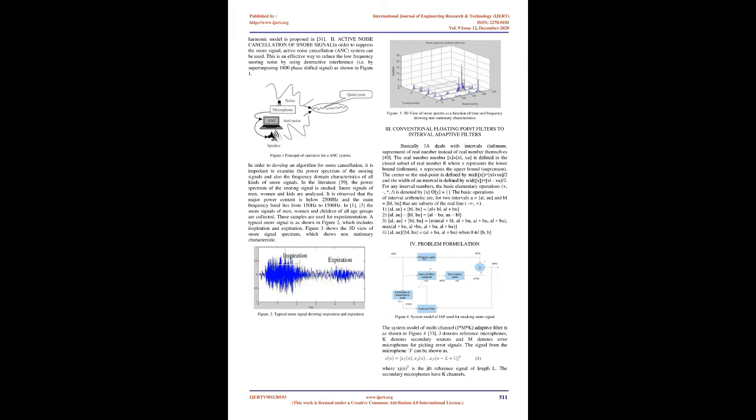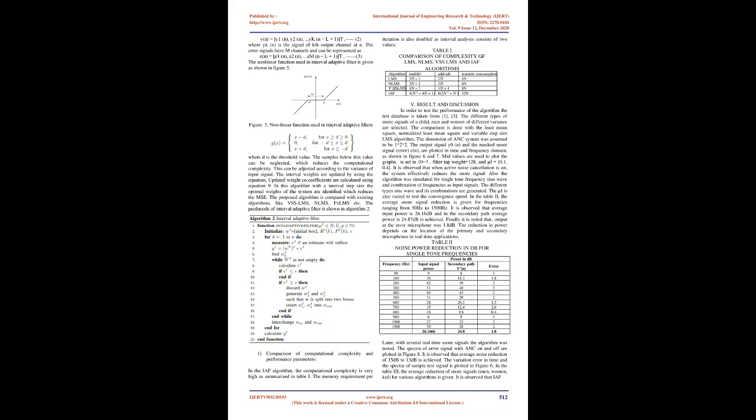The system is bounded under parameter uncertainties so that the gain matrix and its covariance matrix are optimized to give minimal error boundary [23, 24]. The state estimation problems are solved by using interval analysis-based optimization algorithms. It is observed that the bound of IA encloses all types of solutions, with respect to the primitive Kalman filter.